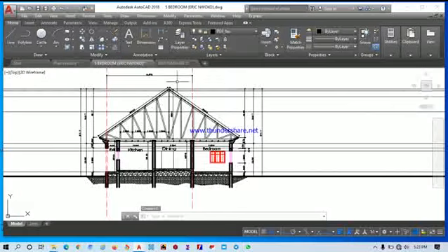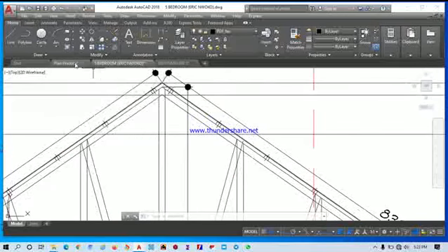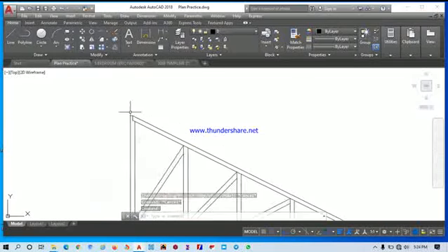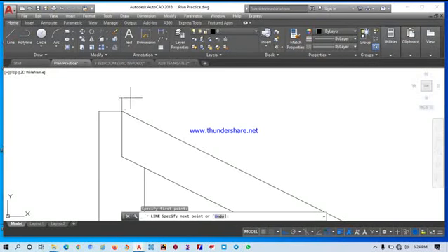Okay. Like I said, this is a typical example of your roof section. You see the lines interwoven, it depends, but I want them to be more clear. So now how to go about drawing our purlin? You turn off your auto mode or you click on shift. The size of our purlin is 2 inches by 3 inches. So the height will be 3 inches while the width will be 2 inches.